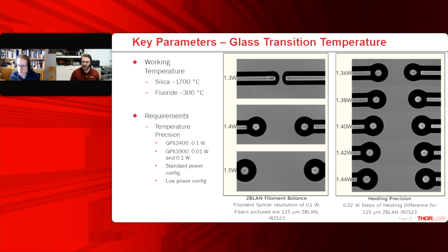Humidity, I think probably could be a bigger issue. I know that at least with the GPX, we're purging that filament body with ultra high purity argon, 99.999% argon, and the H2O content of that purge gas is very low.